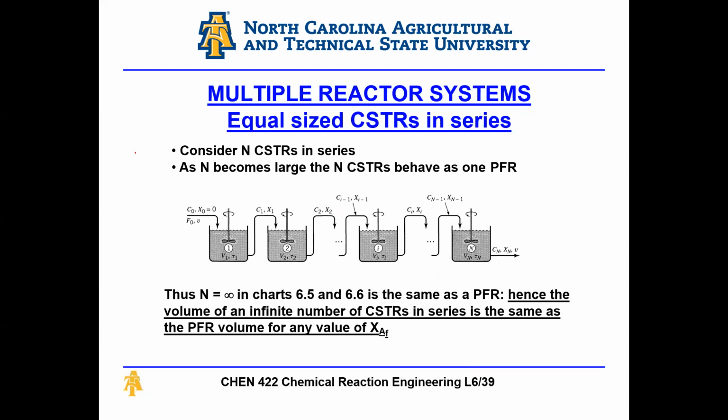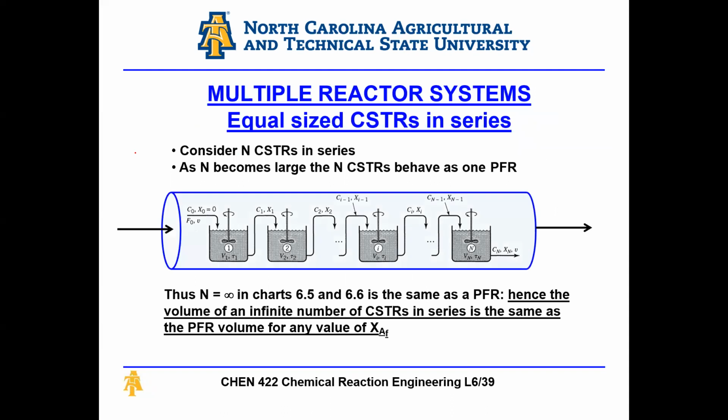The next concept we need to be aware of is having equal size CSTRs in series. And you must know that as n becomes large, n CSTRs behave as one PFR, right? So if I have an infinite number of CSTRs in series, they behave exactly like a PFR. And as the number of CSTRs in series increases, the performance gets much closer to that of a single PFR.